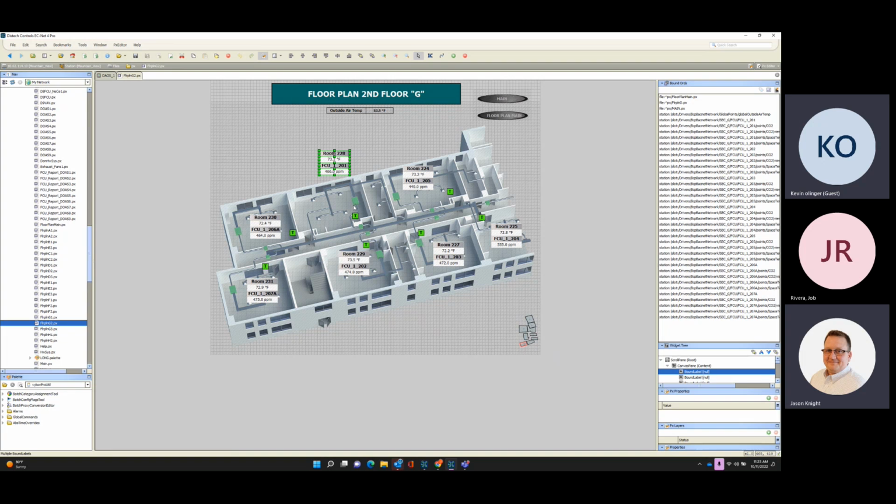They wanted it to just be 200 parts per million higher than the standard outside air CO2 level, which is generally 400 for Portland. And are we monitoring the outside CO2 so we can have a firm differential, or is it just based off of the average that we know it to be? It's just based off of the local area average. Okay. I mean, obviously, forest fire is going to change that. There's other things, but the typical for the Pacific Northwest is 400 parts per million if you're just standing outside.